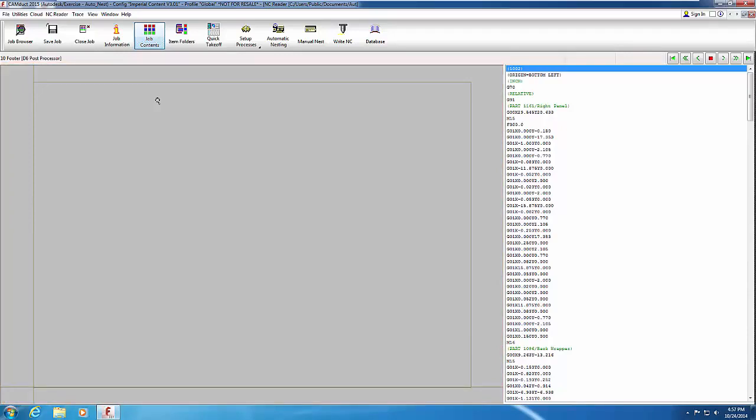This window can simulate the cutting process by showing the tool head path in motion. The display is controlled by the remote control icons on the NC View bar at the top right corner of the window. The controls for viewing the NC work in a similar way to a Blu-ray disc or DVD remote control. Once the simulated tool has been started, statistics appear to the left of the controls. These show the cut length and machining time.